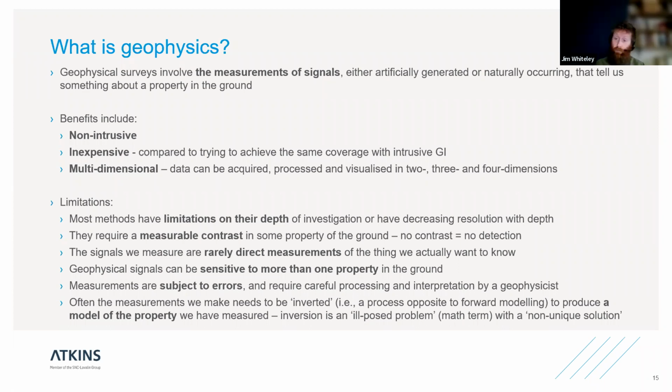Now, a lot of geophysical methods don't have a modeling stage. For example, if you're going out with an electromagnetic conductivity meter, which normally looks like a ski that you walk around on site, or you can tow it behind a vehicle, that's going to just be picking up measurements from the ground in terms of electromagnetic current, which is related to conductivity. And that generally is presented as a plot. And the only processing that needs is filtering of the data, but there's no modeling stage involved.